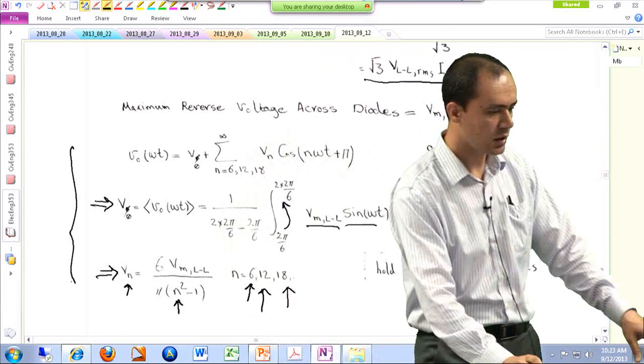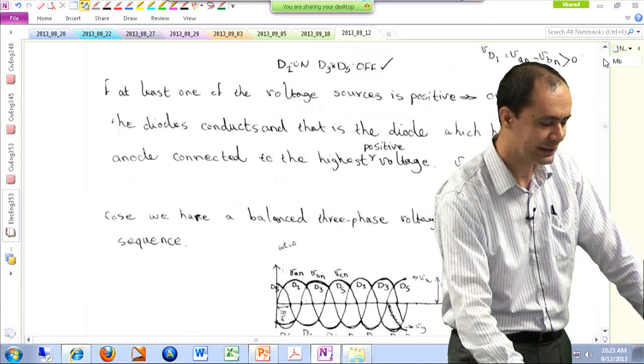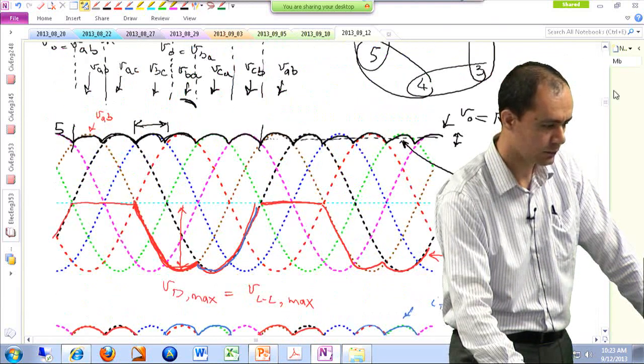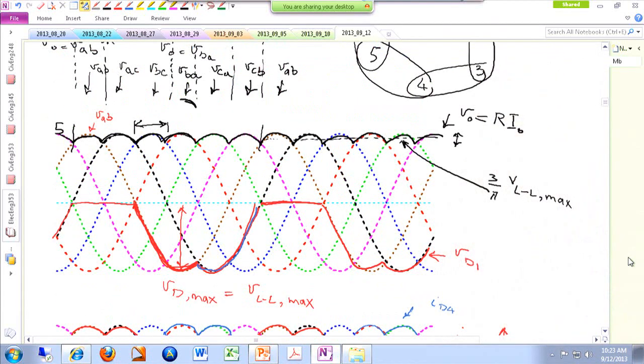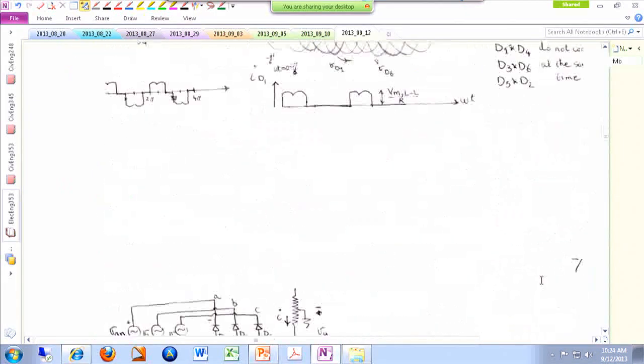As you can see, our output voltage as well as the output current are relatively DC. Okay? There's not a lot of ripple on them. But let's say you have a load which is very sensitive to ripples in the current, and to make that load happy, in addition to your resistive load, you have also added an inductor in series with the load.